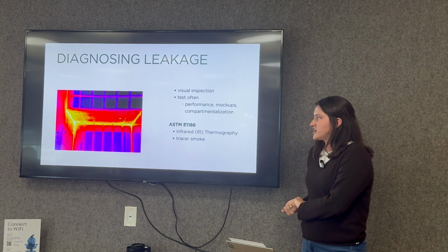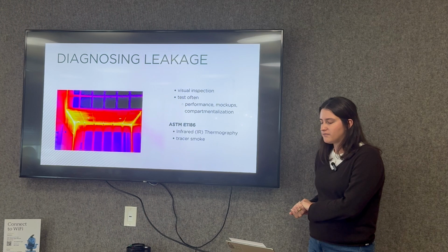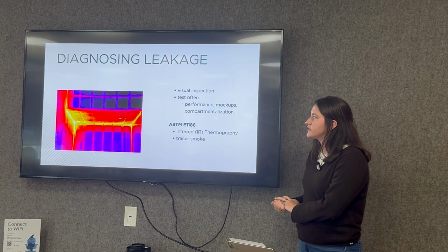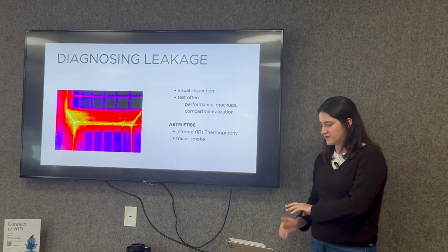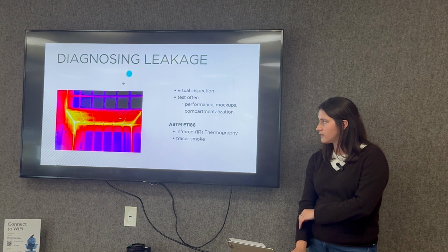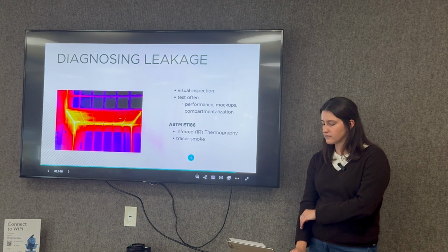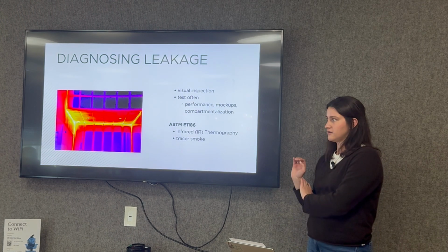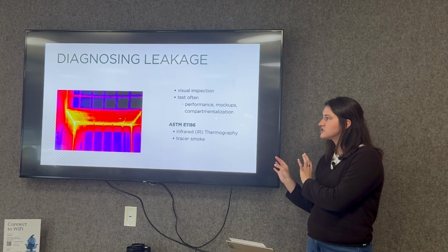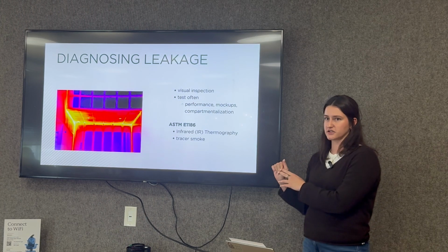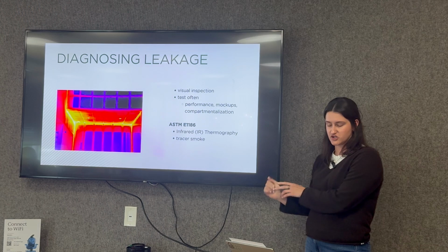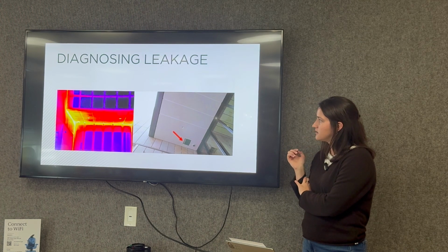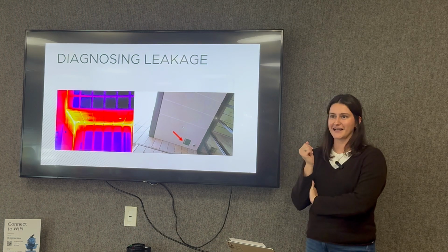So what does this thermal image get us? What does it mean? How is it helpful? And what does this mean at areas where there's uncharacteristic air leakage? So this is a building soffit with, what you can't see in this picture is there's a security camera up in this corner here. But we were lucky enough here that because it was written into the specs, that anywhere we had any sort of ambiguous results for the air leakage testing, the contractor was responsible for conducting exploratory openings at these locations. So after our test, the contractor went back and made an opening in the soffit where we saw this air leakage. Does anybody want to guess what we found?